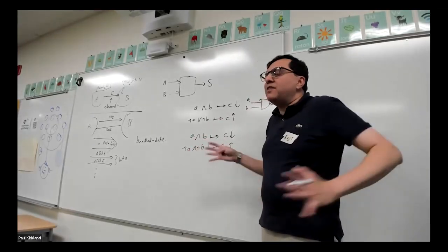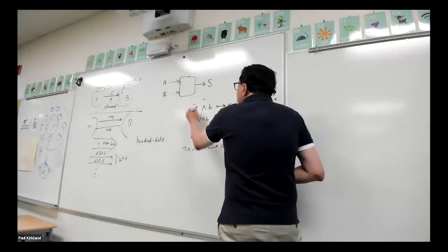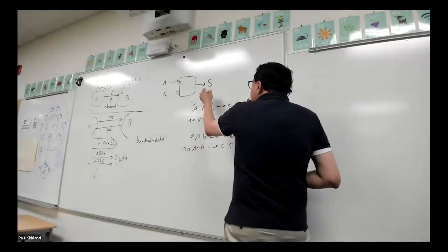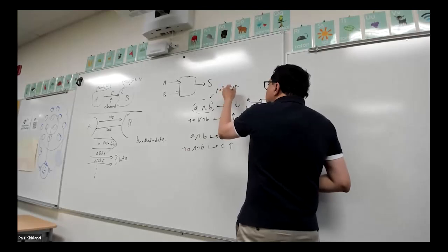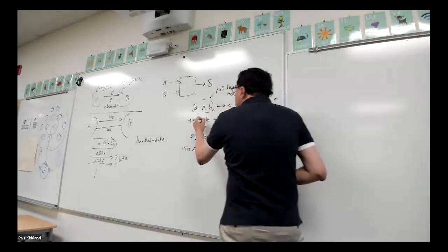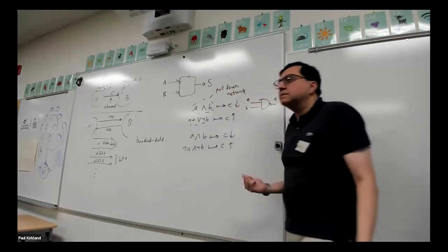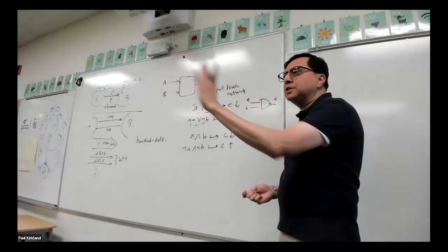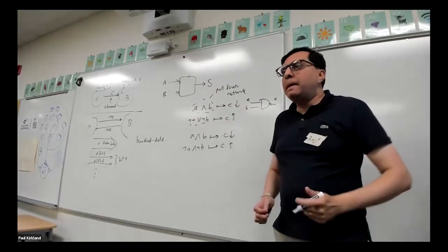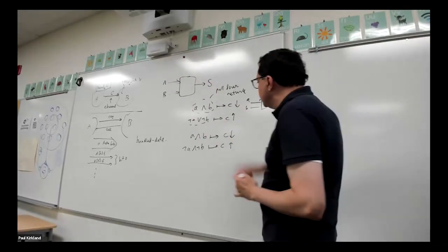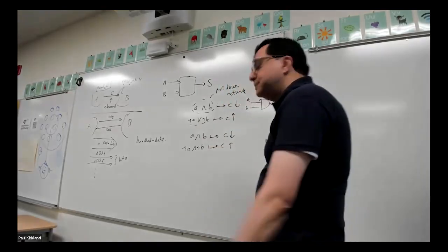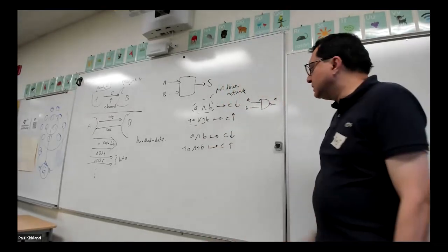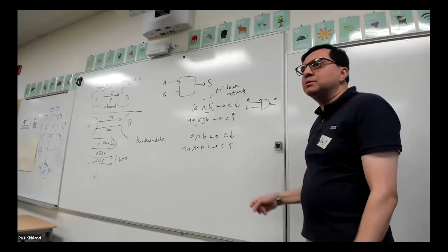Okay. So for those of you who like doing circuits, this is the pull-down network. Right? And this is the pull-up network. That's it. You just write the Boolean expression for the pull-up and pull-down. But those two aren't the same, right? Which two? The NAND gate and the... No, there's an AND here instead of an OR. Oh, okay. Yeah. This is sometimes called a C element, inverting C element, Muller C element.